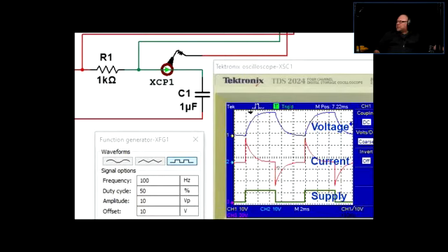So what happens? The current rushes up like crazy, because the capacitor acts like a short circuit. Of course, if the component acts as a short circuit, there is no voltage between the terminals of that device. So there's going to be no voltage because the current is at the maximum right there. It just rushes like crazy. Right?